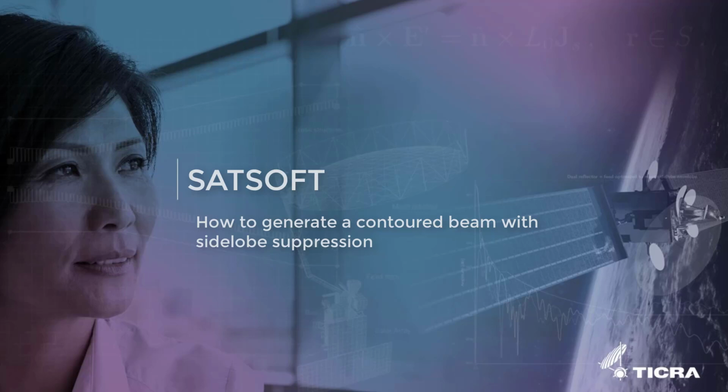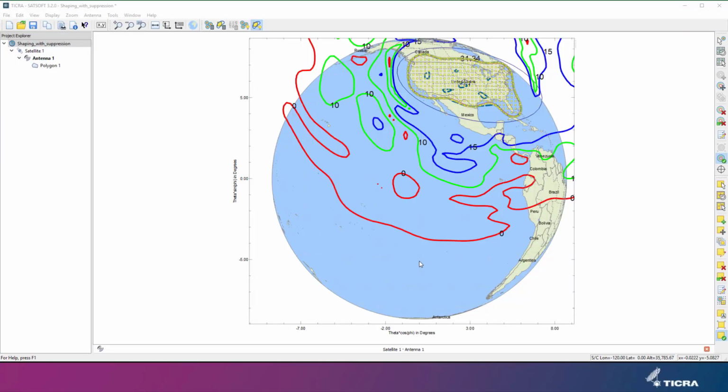Hi, and welcome to this SATSOFT how-to video, where we'll illustrate how to set up sidelobe suppression as part of generating a contoured beam. As an example, we'll consider an analysis of a contoured beam over the contiguous US or CONUS as produced with a shaped reflector antenna model that was introduced in SATSOFT 3.2.